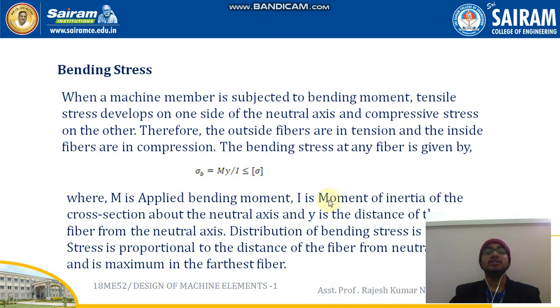Here the moment of inertia value will vary depending on the cross section. The distribution of bending stress is always linear and the stress is proportional to the distance of the fiber from the neutral axis, and it is maximum in the farthest fiber.